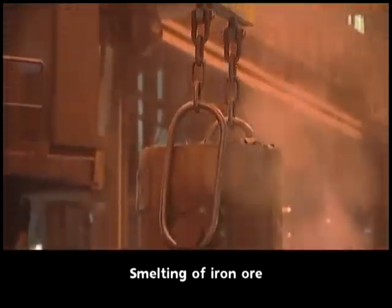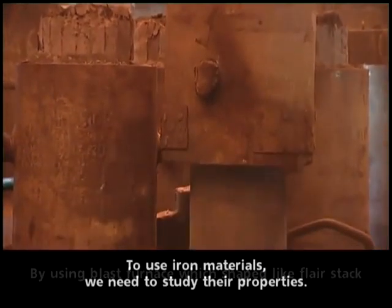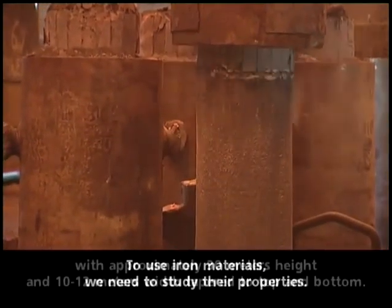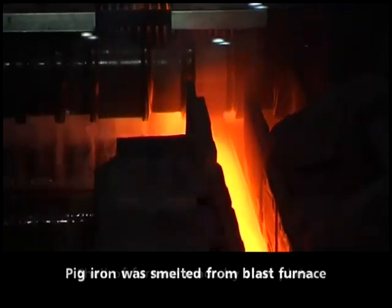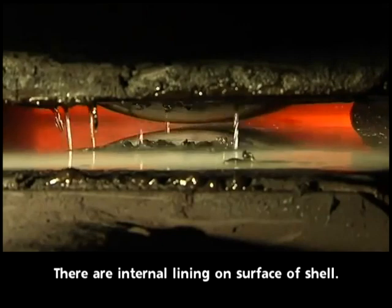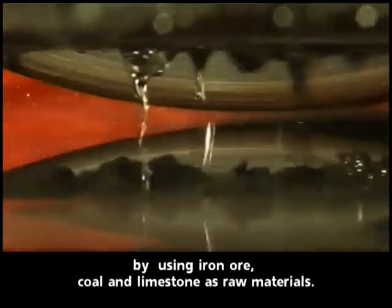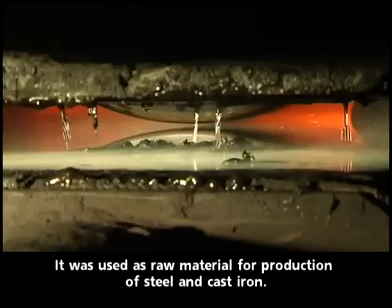Smelting of iron ore uses a blast furnace, which is shaped like a flare stack, approximately 30 meters in height and 10 to 12 meters in width, tapering toward the top and bottom. The shell of the furnace is made of steel plate. There is an internal lining on the surface of the shell. This is to keep the inner surface thermally resistant.